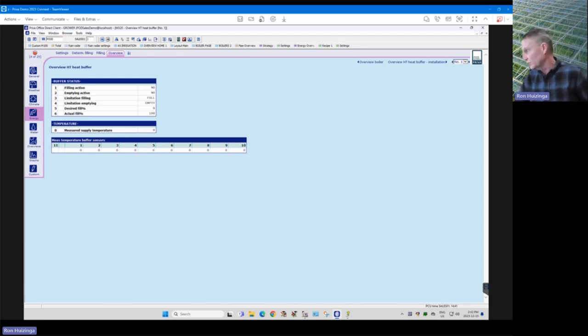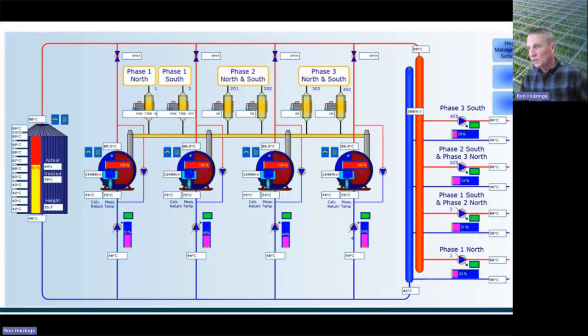But you see from this example that it's not always going to be perfect. There's usually always a couple of sensors that are kind of in between. So you've got 42, 43 in the bottom 4, and the top are all close to 89. So there's going to be a couple there. It's not exact layering in the tank, but if the top 4 sensors are at 90 and the rest of the sensors are at return, then yes, it'll be 40% full of heat.